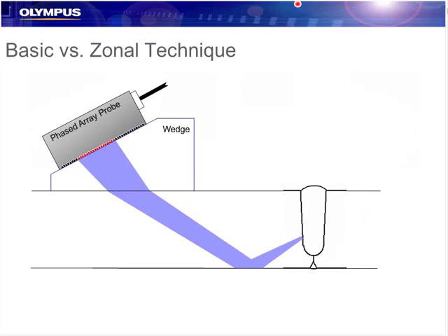When we look at typical pipeline joints, often they're engineered with very narrow bevels, so 5, 10 degrees. Even though phased array, sectorial scans, and linear scans are great, they can provide a lot of coverage and detection capability, they're still pulse echo ultrasonics. So when we have an incident angle that is so narrow, it can be very difficult to get the sound back to the probe, especially for the fusion line. So this is where, from a technique perspective, we might want to look at a zonal technique or a pitch catch technique. If we had normal pulse echo, this might never come back to the probe just because of the narrow incident angle.